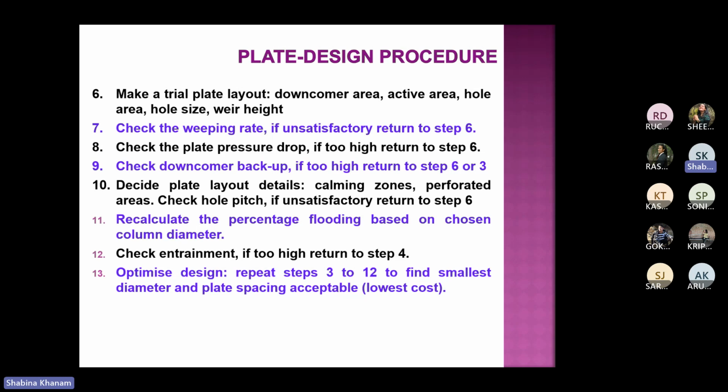And when we compare sieve tray and valve tray, sieve tray is much simpler and cheaper in comparison to valve tray, and the functioning of each type of tray we have discussed. If the operating parameters are such that it can be done with the sieve plate, we should always prefer that, unless you are operating at very low flow rate.